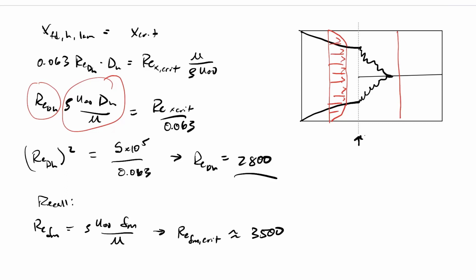First of all, we have this viscous sublayer forming down here, and if we remember, that is where basically all the velocity gradient is. That's true whether it's external flow or internal flow. So the velocity profile is going to look something like this, with a really steep gradient right next to the wall.